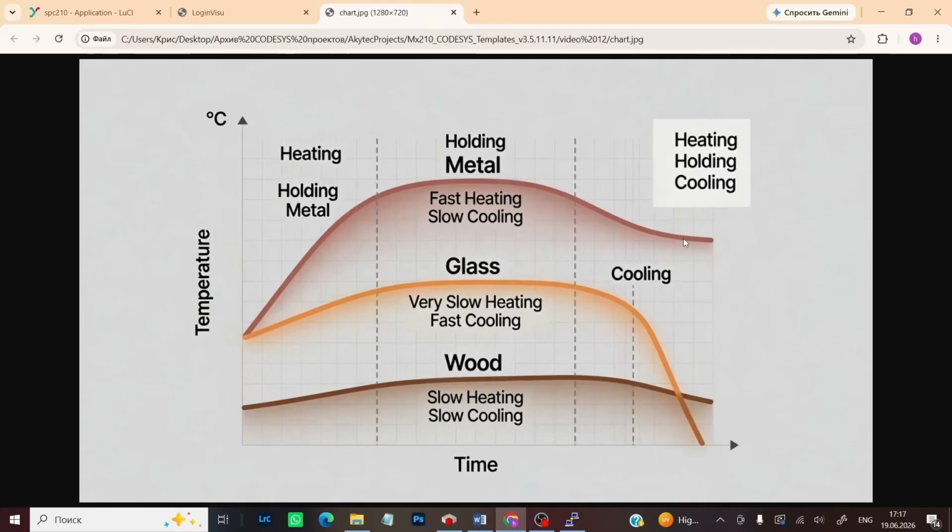Even though after sterilization there are no viruses left inside the chamber, there may still be various dust particles and oxides. We also didn't consider models for regulating safe heating and cooling rates dependent on the type of sterilized instruments and their thickness. For example, when heating a sterilized instrument, its surface heats up faster than its cold center. So during the heating phase, the surface of the material expands, causing the center of the material to stretch while the surface compresses. During the cooling phase, the opposite happens.